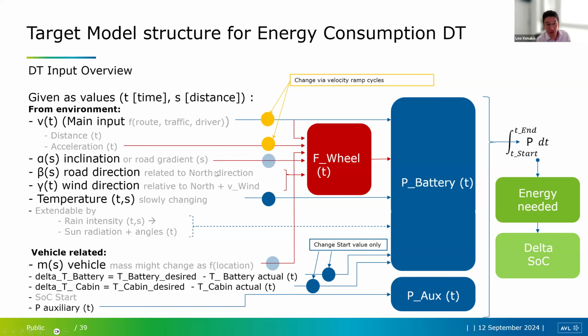Yes, definitely. When you're just driving the vehicle normally, as the vehicle speed goes up and up, the amount of fuel that you use, if it's a normal vehicle, or the amount of energy you use in an electric vehicle, can go up really quite a lot, especially at higher speeds. This is because of the air resistance. When you're riding a bike, for example, you feel this. And of course, with a truck, you have quite a large frontal area.